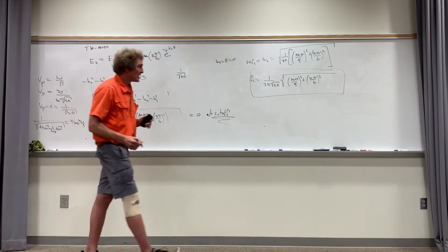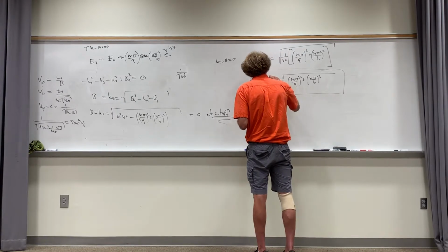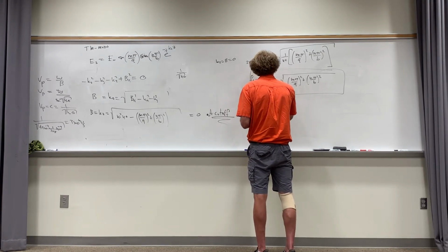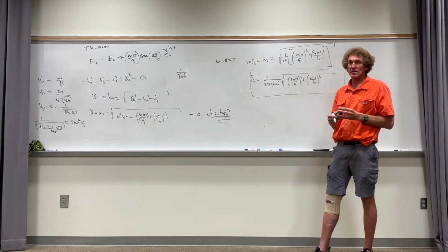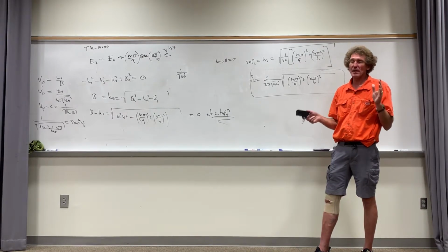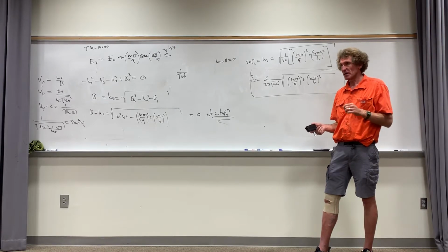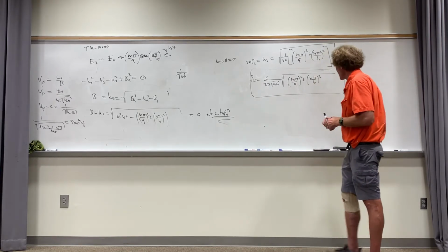What I'm really getting at is I can replace this 1 over the square root of mu naught epsilon naught with c. I can put c divided by 2 pi, and then downstairs I can put the square root of mu relative epsilon relative in the guide. Generally speaking, epsilon relative and mu relative are 1. Epsilon relative can get a little higher if it's a dielectric, but a hollow air-filled guide has epsilon relative of 1. Follow me, guys?